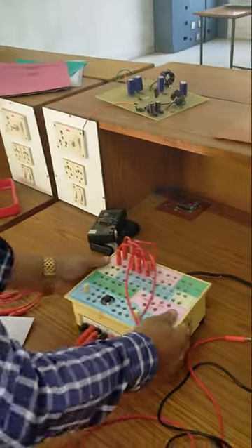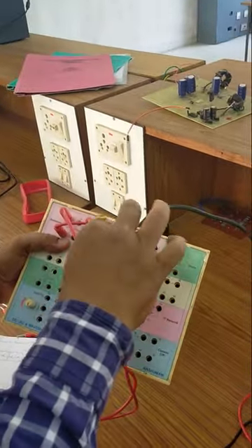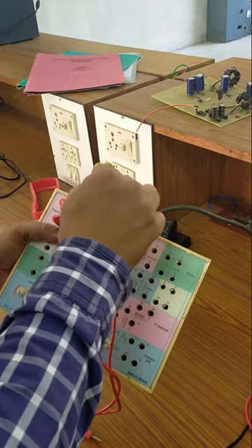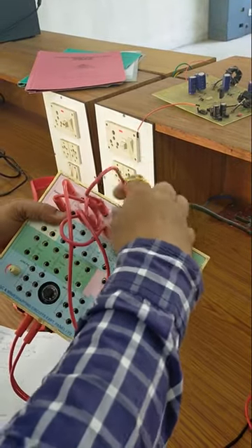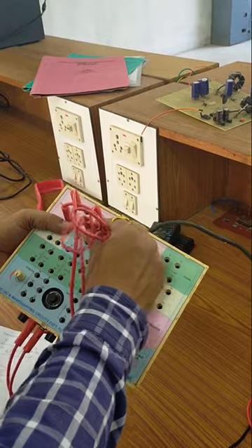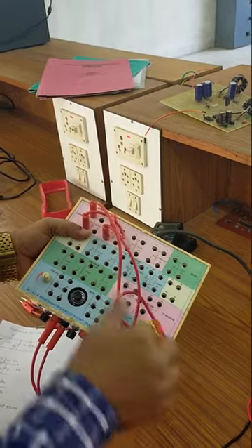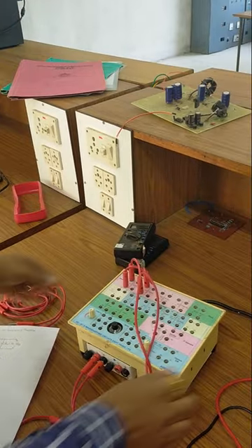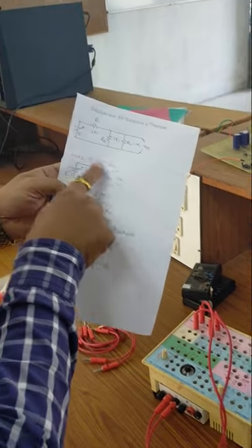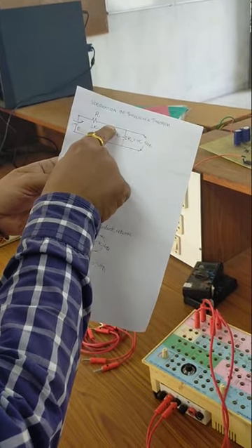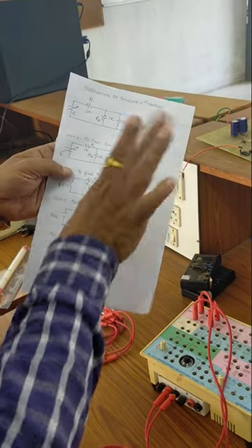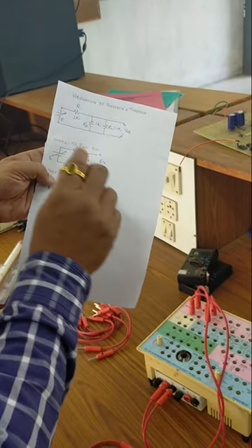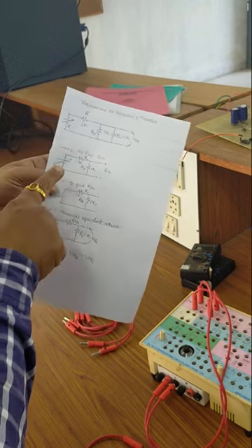We will remove this branch, means with the help of this circuit, we will simply disconnect the load resistance. So the circuit looks like this. Listen, the circuit looks like this. Means we have removed RL, the connection parallel with R. Now this voltage is, as usual, given as 15 volt.